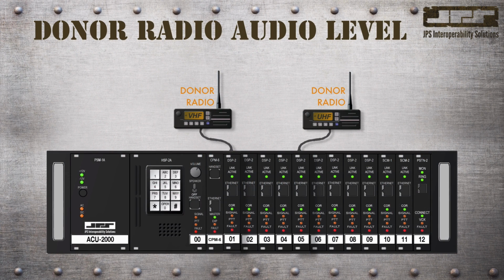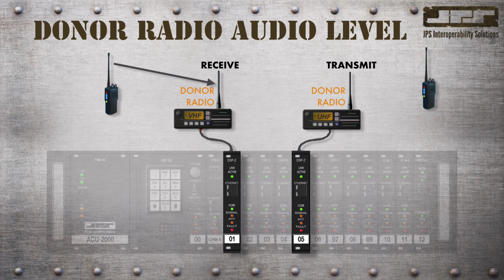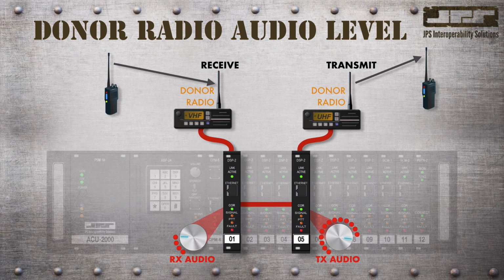The ACU DSP and ACU radio resource interfaces of the ACU interoperability gateways and modules contain an audio gain control that will assure that the receive and transmit audio levels are at the proper levels, such that when shared, the audio level will not over or undermodulate disparate radio systems.